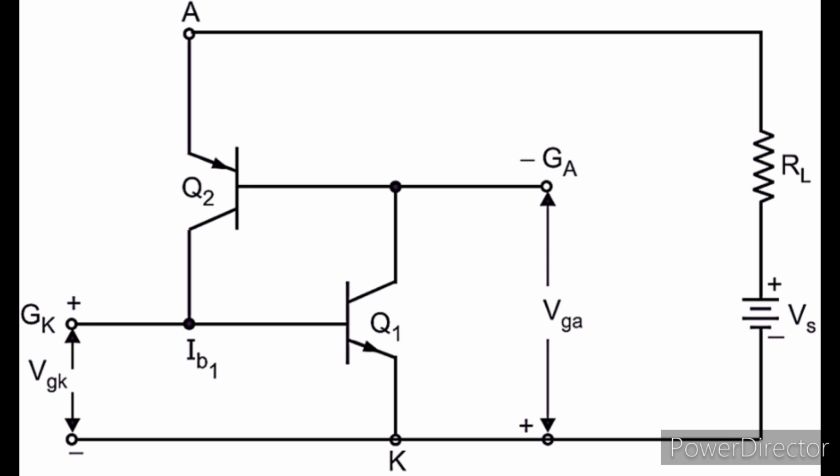Now, when we apply a positive pulse at the gate terminal G1, the holes in the P2 region are pushed towards the N1 region and the electrons of the N1 region are attracted towards the P2 region. In this way, the reverse bias gets reduced, that is, the effect of the electric field is removed, so the device goes into the on state.